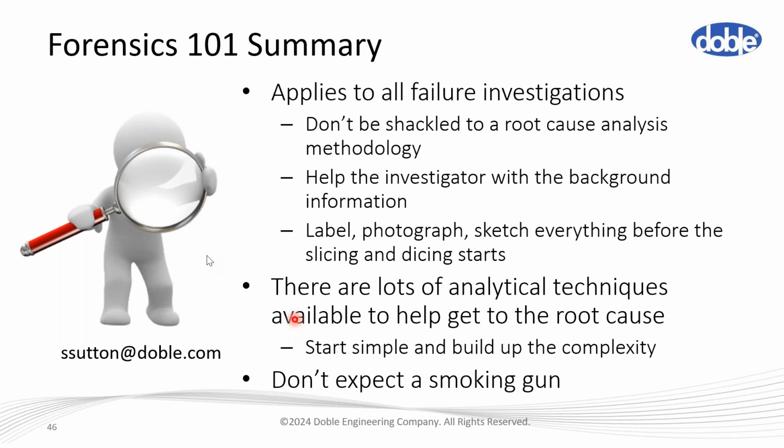Usually, if we think about it, the cables are factory tested, the joints are factory tested before they arrive at site. Most of the problems with cable circuits are either caused during the installation, so it's a defect in the accessory, so partial discharge is very good at picking that up, or it's going to be where somebody digs into the cable and damages it from the outside.